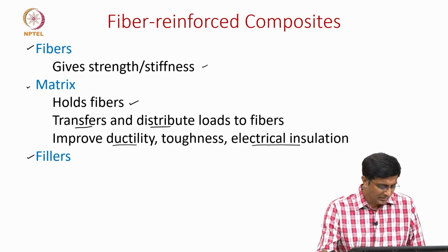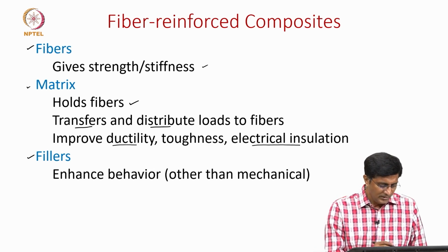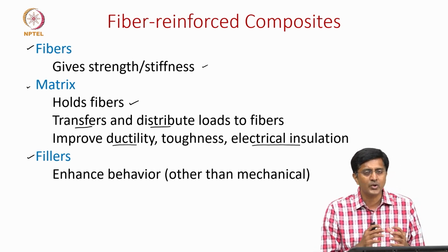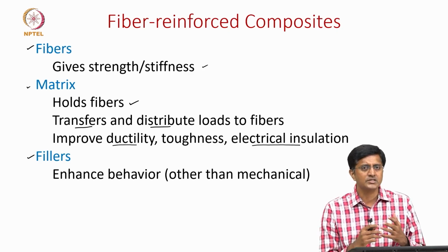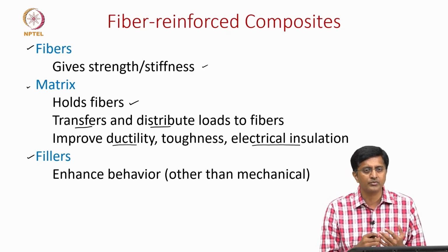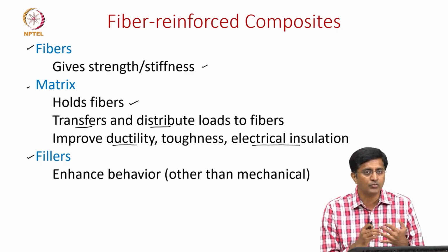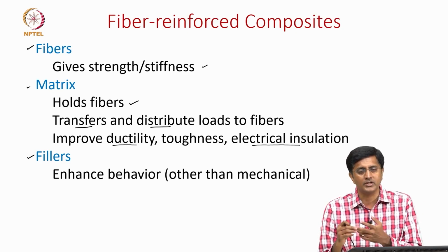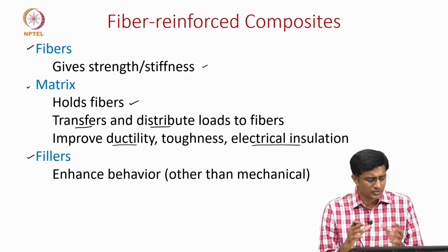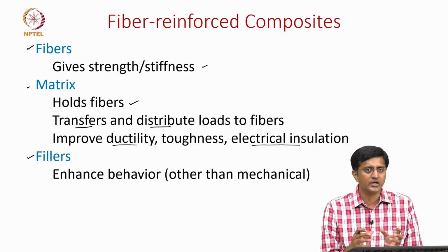And lastly, regarding the fillers, they are not used to enhance any of the structural properties of the materials, but they take care of other properties, such as how we reduce the weight of a composite, or how we ensure that the composite does not degrade when exposed to UV or when it is close to fire. There are many other filler materials; we will come back to that in greater detail later.